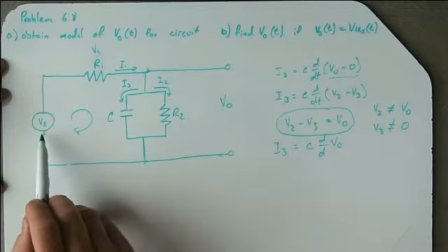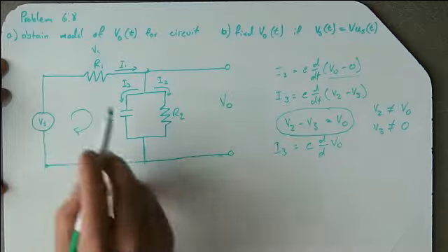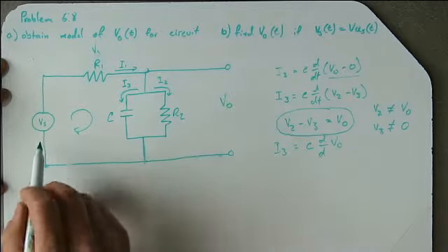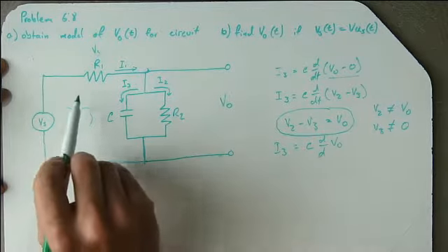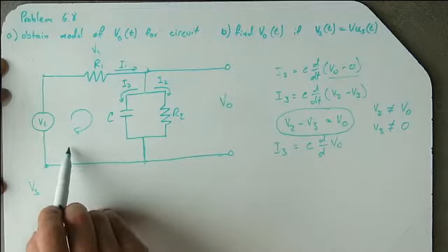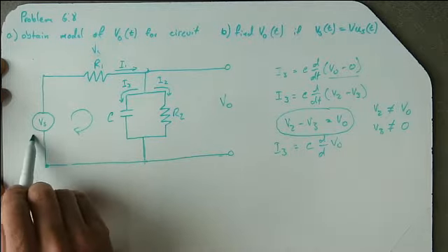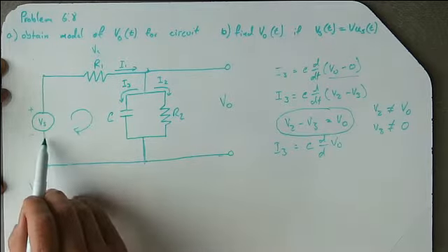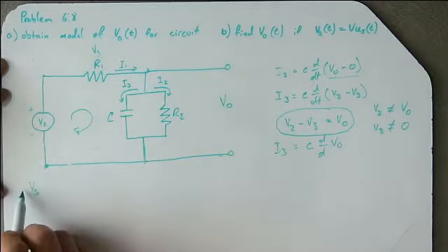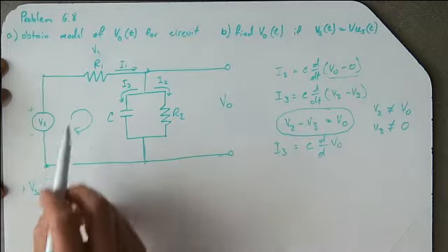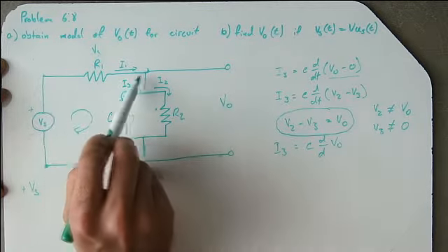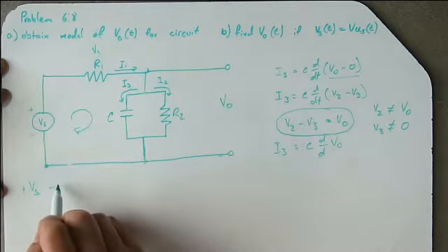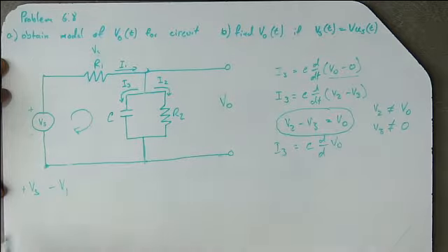And so then we can do Kirchhoff's voltage law, and we just have Vs, and this is a positive Vs. If you follow the current, when you go across a battery, or some voltage source, you go from negative to positive, you're going up in voltage. So we have a plus Vs, and then we go across a resistor, so we're going to go down in voltage, minus V1.